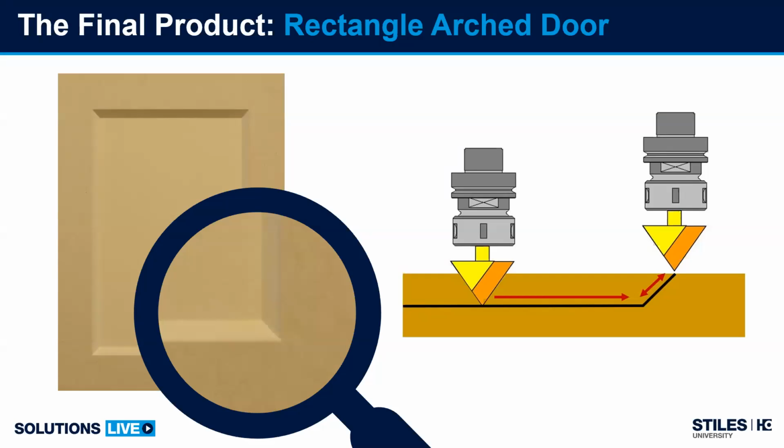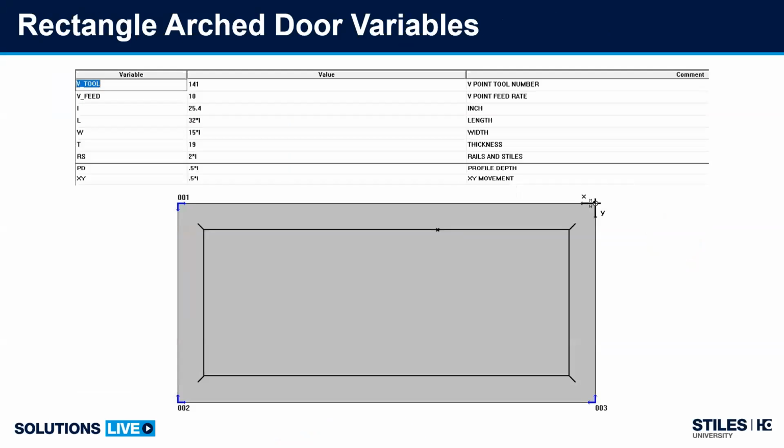So when we make that XY move, if the XY movement is too small, then the tool comes up in Z, the corner is going to tend to bow in. So if you see the corner starting to have a small radius inward, we need to make that XY movement longer. If you see the corner starting to flail away or radius out from the corner, then your XY dimension is too long. So again, if we make a variable just for that dimension, it makes it much easier to calibrate this. And once you get one corner perfect, then naturally the other 3 corners are going to fall in line. So here's my variable list.